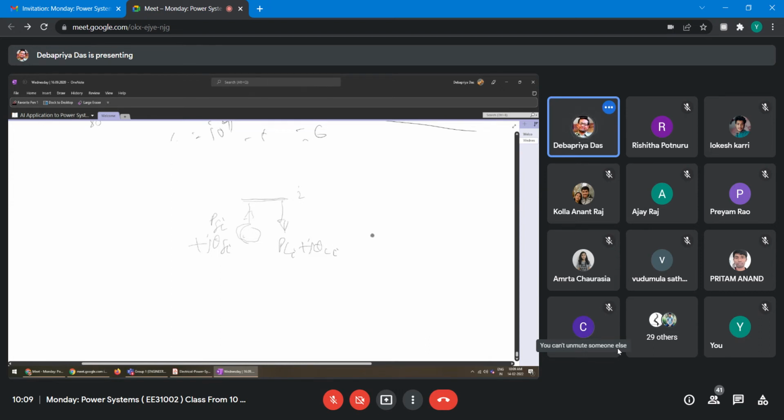Now, if you take the net injected power at the ith bus, PGI is injecting and the load is consuming power. I'm just showing it by arrows. So here it should basically be PGI minus PLI for real power, and for reactive power, j times QGI minus QLI, because in this direction power is being injected and load consumed, so net is PGI minus PLI.